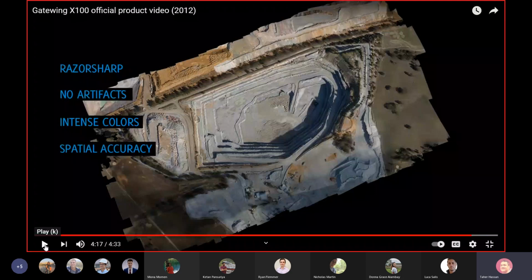One more thing I need to remind you: having a drone fills the gap between conventional surveying, like total station and GPS, and conventional aerial photogrammetry, where you need a big aircraft and you hire a pilot and so on. So right now, you can use photogrammetry on a small scale, even flying a drone above a house and creating a 3D model of a single house, which was not available 20 years ago.